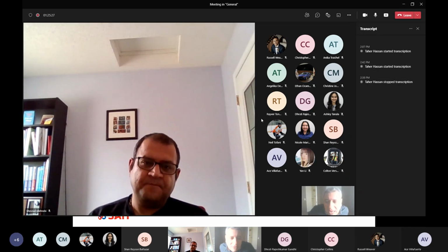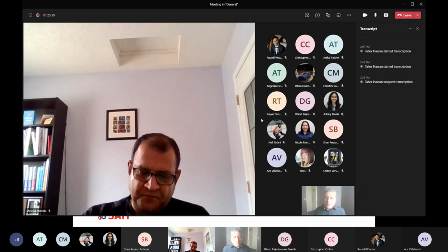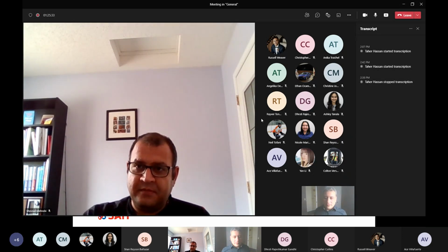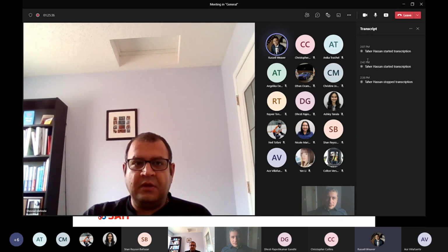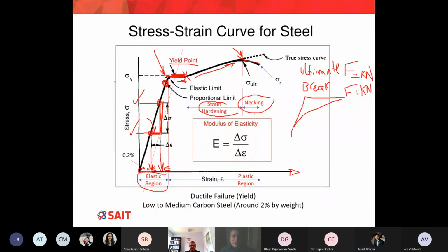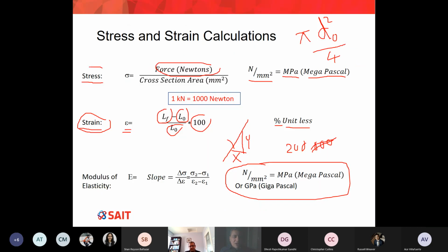Masoud, you seem to know that. How is that? Could you just use the area of the object that you're testing to find the stress? The force over the area of the object that we tested. Yes, sir. Thank you. So here we go. Anytime you want to find stress, you find the force divided by the cross-section area, and the cross-section area is right here. So A0 is equal to pi multiplied by D0 squared divided by 4.